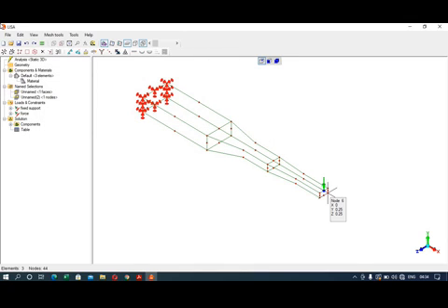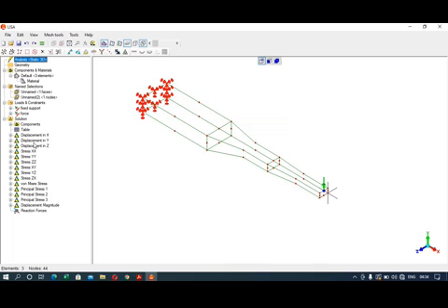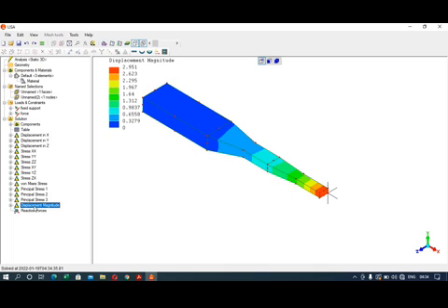OK. So now you can click on the right click on the solution and solve. Okay. So here you can check the displacement magnitude, which is 2.95, and the von Mises stress value is 4.07 into 10 raised to the power 6.